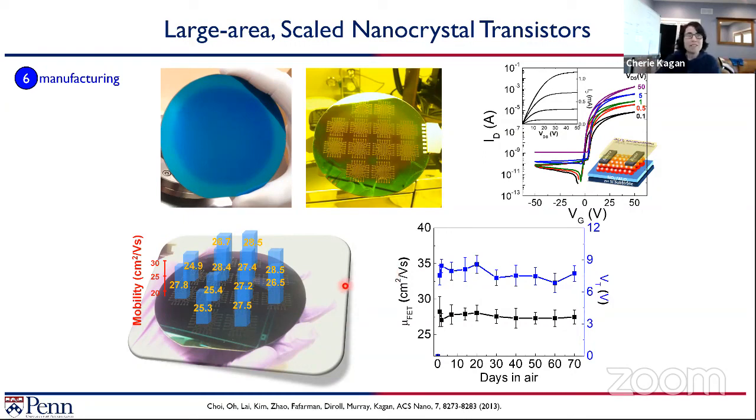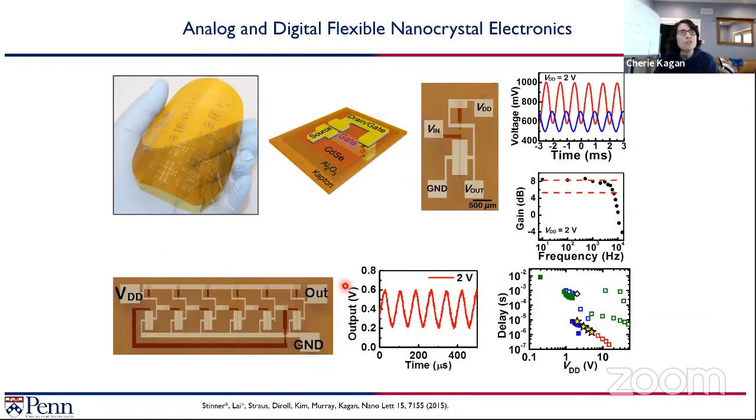So then we went back and said, if we can do that, photolithography gives us much smaller dimensions. And so we could remove some of these parasitic effects of capacitances and basically revisit the idea that we could make, this is again showing the source and drain, and we developed a via process, which is actually harder than it looks, to cut through to the gate electrode. But this is now our next inverter, which we now have to look at under a microscope instead of by eye, fortunately. And then this is the ring oscillator.